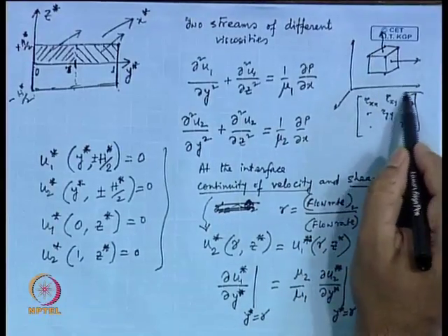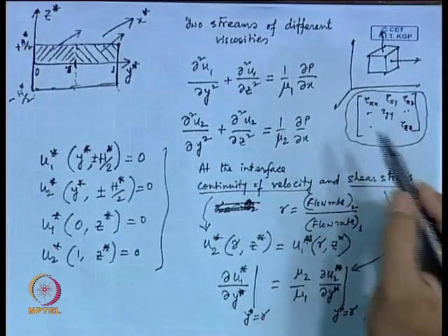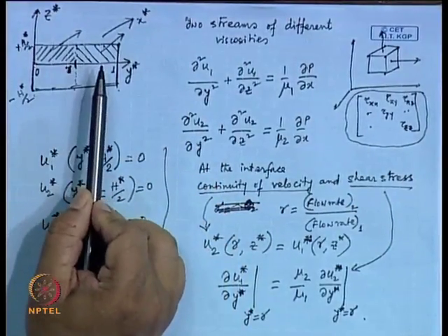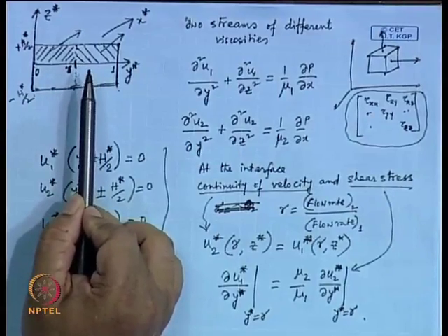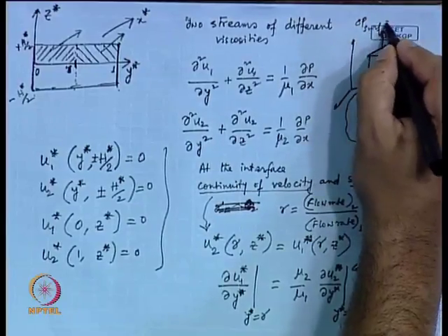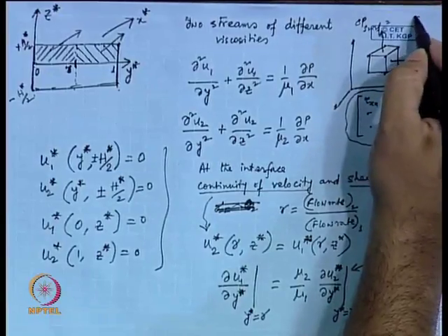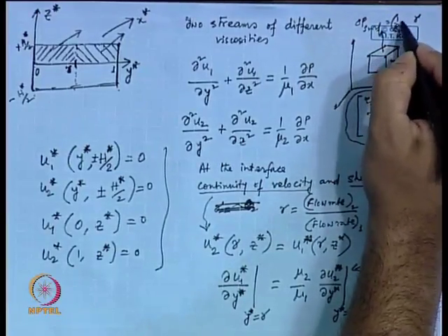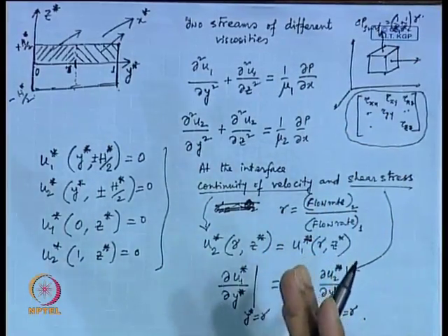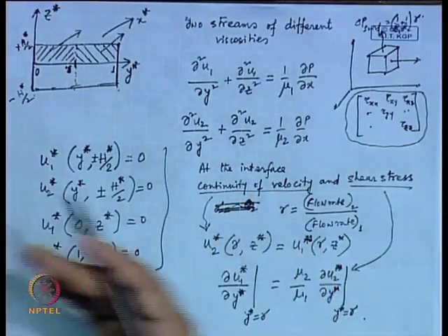So, this is the stress tensor. If it had been an immiscible phase, then you would have to equate the normal component, and bring in the Young-Laplace pressure: delta p surface is equal to the surface tension times 1 by r1 plus 1 by r2. You would have to consider that aspect at the interface if it were two immiscible fluids.